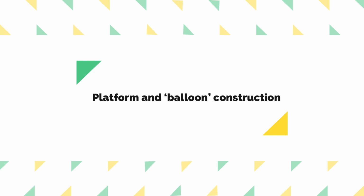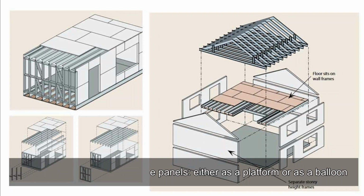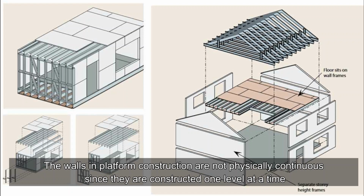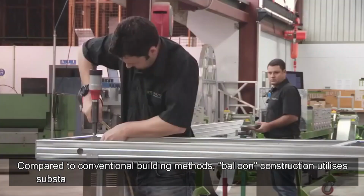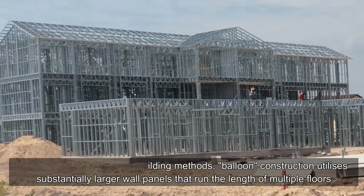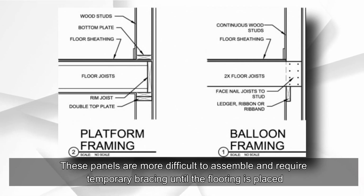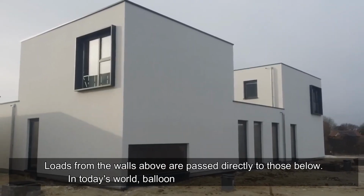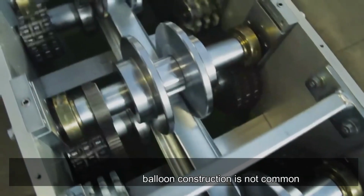Platform and balloon construction. There are two ways to arrange panels, either as a platform or as a balloon. The walls in platform construction are not physically continuous since they are constructed one level at a time, as seen in the figure. Compared to conventional building methods, balloon construction utilizes substantially larger wall panels that run the length of multiple floors. These panels are more difficult to assemble and require temporary bracing until the flooring is placed. Loads from the walls above are passed directly to those below. In today's world, balloon construction is not common.